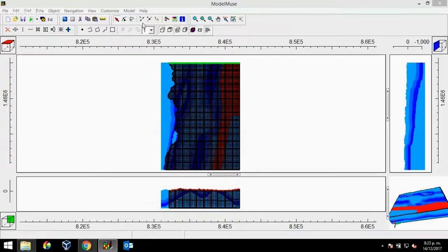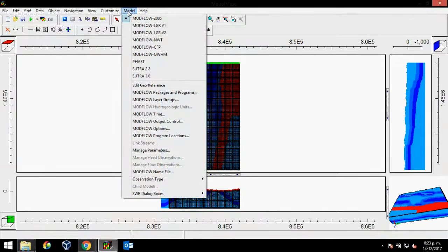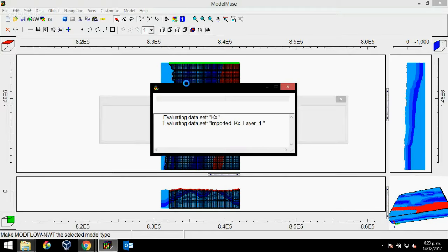Okay. After that, we're going to change the solver that we're going to use in our example, because I'm going to select the Newton-Raphson algorithm to solve this problem. I have done several examples, and the convergence of the Newton-Raphson for this example is faster than the preconditioned conjugate gradient. We have to wait a few seconds. They are converting all the information to the Newton-Raphson solver.